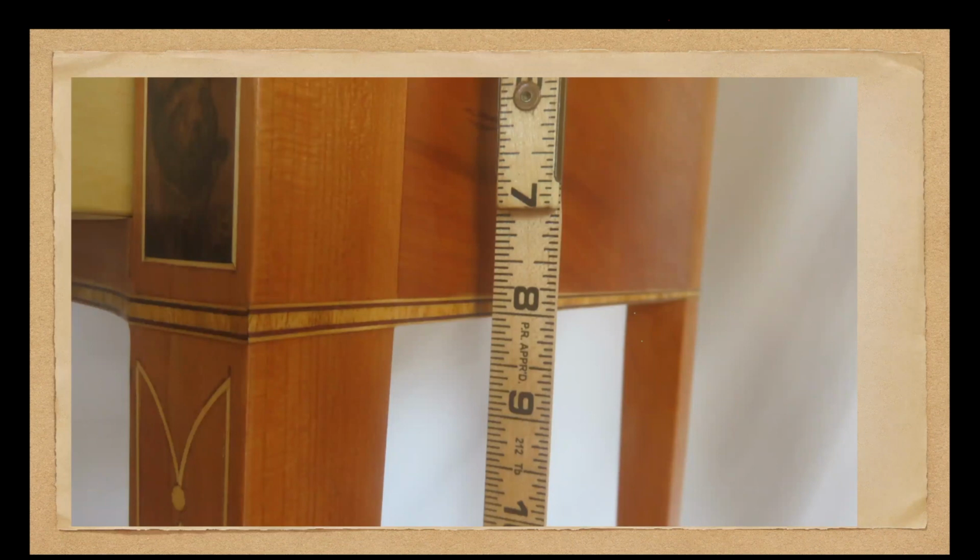Also, there's stringing around the bottom, and part of your thought process has to be, when do you add the stringing? You need to think about that as you are constructing and gluing your pieces of the table together, so that they can be coordinated, because it's really awkward to have to cut a small rabbet at the bottom of that apron once it gets assembled.